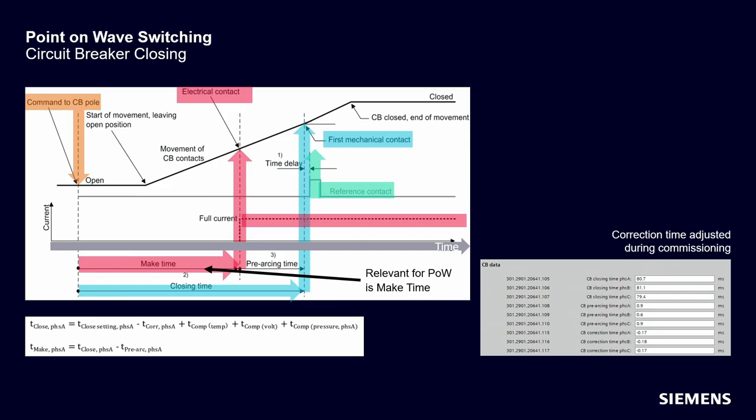These parameters are available from circuit breaker data. Also, pre-arcing time for each phase must be entered. These are the parameter numbers 108, 109, 110. On the diagram, you can see the blue arrows, which are showing graphically measured CB closing time.